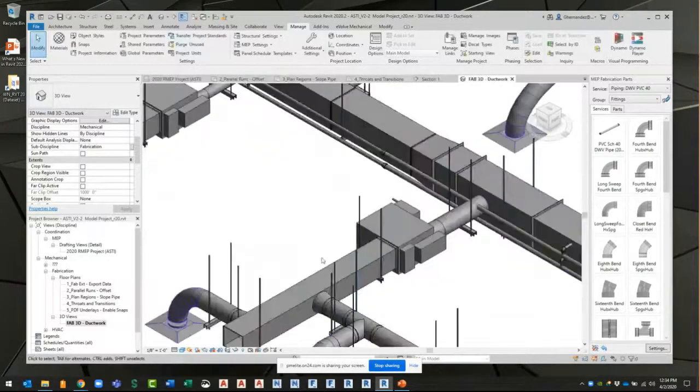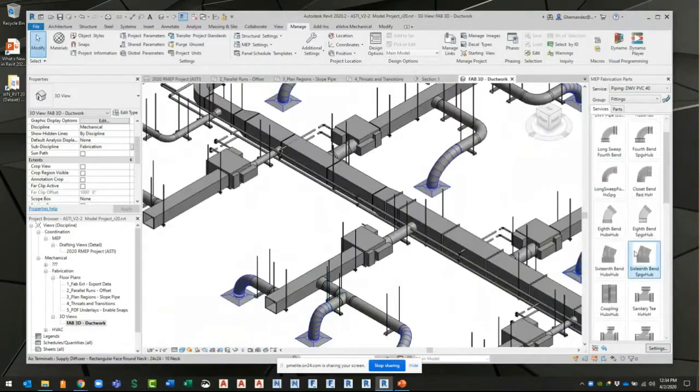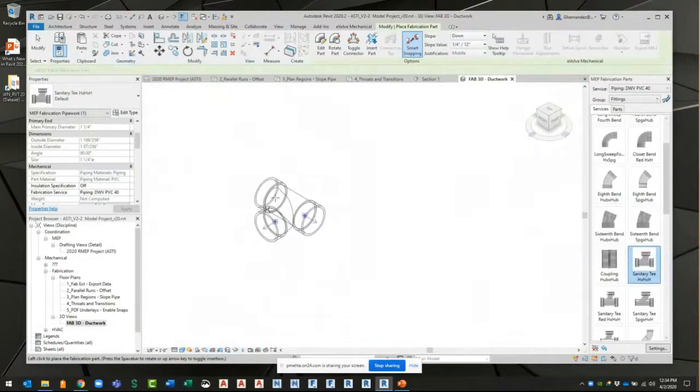One last one for you guys real quick, if I can show this to you. This is a cool one. If you hold the control key down and the space bar and tap the space bar, it rotates the part in the other direction. So space bar does this, and we kind of worked through that, but holding the control and space together rotates it in the other direction. So it's kind of like a 3D rotate, which is kind of cool. Then you can rotate it this way and then rotate it that way, control space bar, right? That's another little tip that I just remembered.